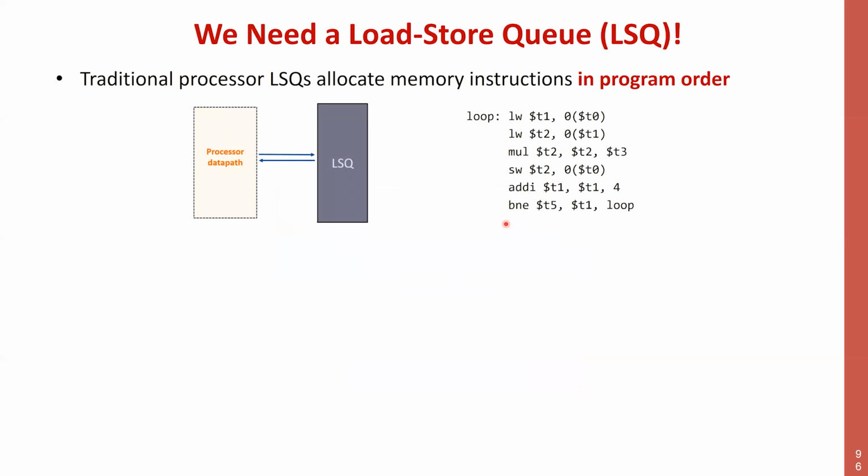And actually, I think that in the slides, there is this comment that in practice, people do it in a different structure that is essentially equivalent to the reorder buffer that I showed in the slides, but is actually a load store queue that is specialized for this job. Again, the job is the same, the place where it is done is different.